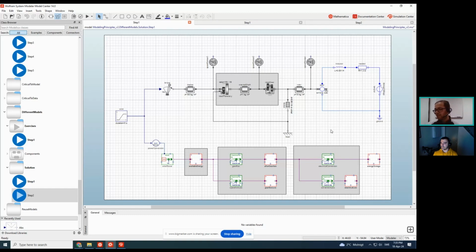What happens is they read the FMI format that your model is shipped with, and then they create components based on their tools. They take the equivalent equations and recreate the component in their tool, which you can then simulate and use as a component in that tool. So yes, when you share it, it is meant for simulation.